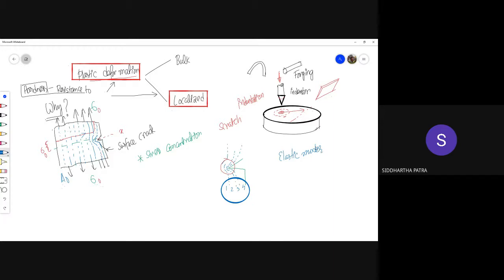It is always deforming elastically, but no material does. So even the ones we classify as brittle material have a tiny bit of plastic deformation, extremely tiny, but there is some. You'll be surprised to know even glass has a certain amount of plastic deformation. So the point is, in real life, the material responds in a slightly different way. The stress doesn't go to infinity, but, let's say this one is the crack tip, the stress still reaches a very high value.